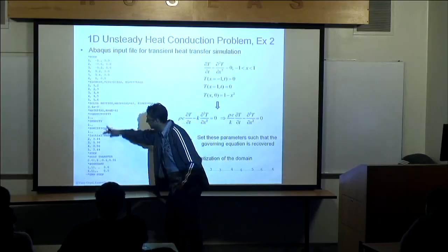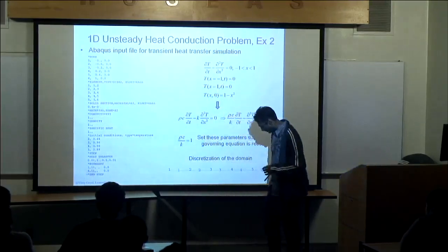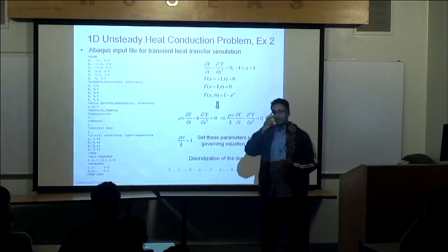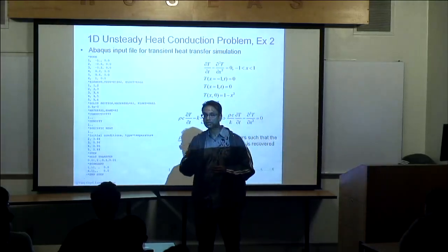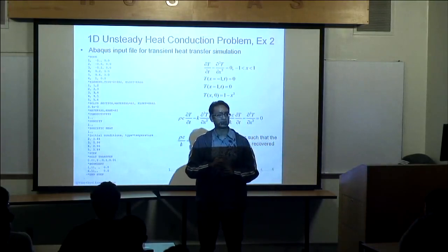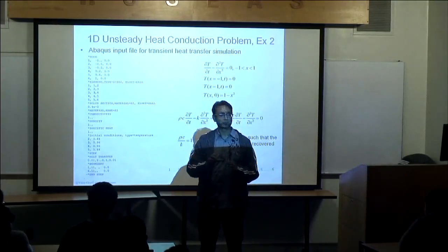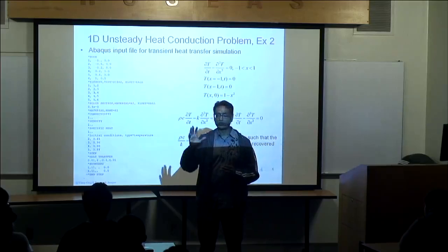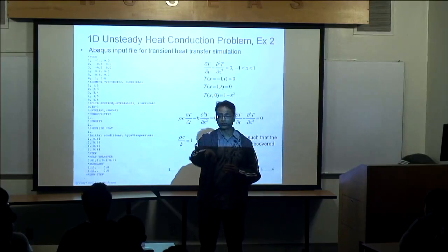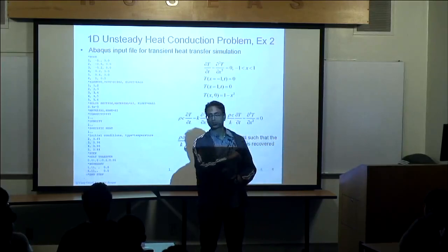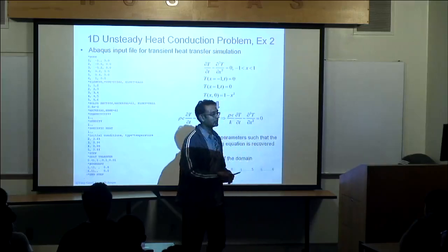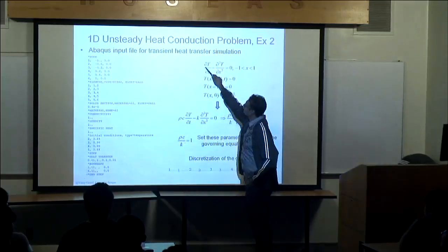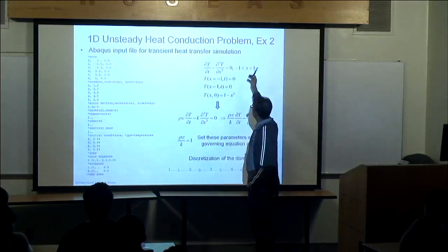All right, before I continue here, I want to point something out, because there's something exciting about Abaqus. You can actually fake Abaqus to solve non-heat transfer problems if you understand how Abaqus is doing it. Let's say I want to solve an electromechanical problem, or, just come up with a problem that Abaqus doesn't solve, because I think Abaqus solves too many things, so anything I say, they probably solve it. You can fake Abaqus into using the heat transfer module to solve something else that has a partial differential equation that looks like that. As an example, say I made up this differential equation.